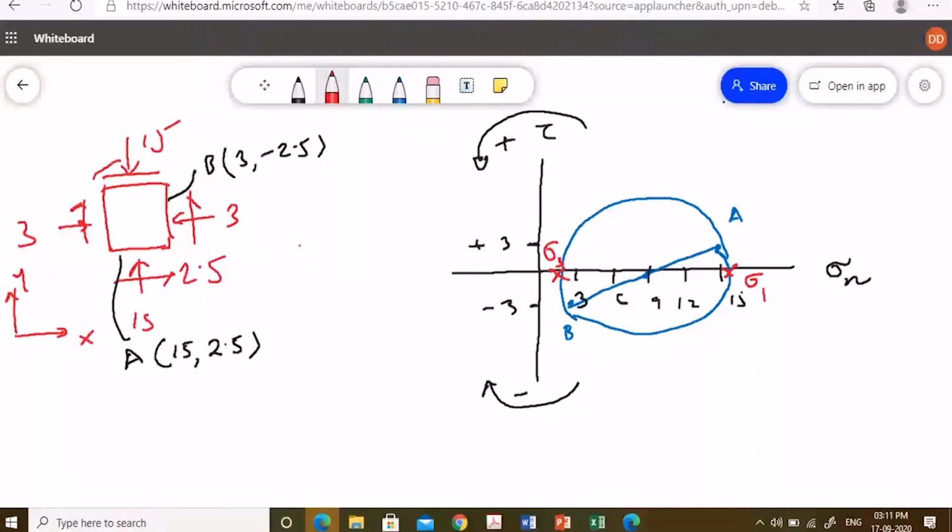Now if you ask me what is the angle from the x-axis, now you can see the x-axis is towards this A, because the A plane is in this case orienting towards x-axis. So this is the angle towards sigma 1. So you measure this angle, whatever you get, you divide it by 2.